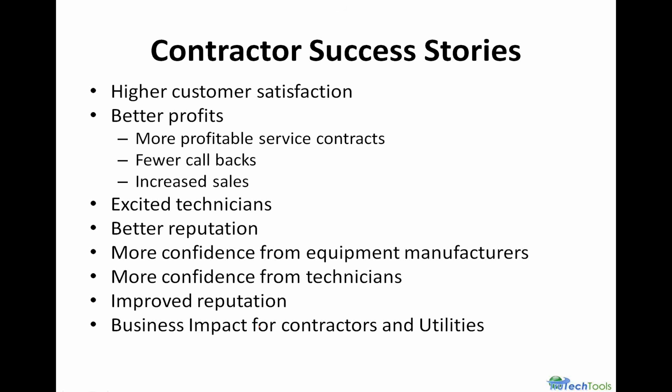Better reputation. You have a lot more confidence in your equipment manufacturers that the equipment is doing what it's supposed to do. I've seen time and time again, in fact, I've never seen a piece of equipment that, if I could get the airflow correct and the charge correct, didn't output the correct capacity. You've got to remember that the manufacturer's engineers and AHRI tested it, so there's two sets of eyes on that thing. It should darn well operate the way it was engineered to operate.